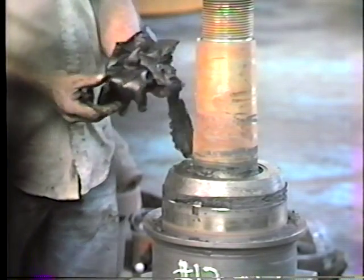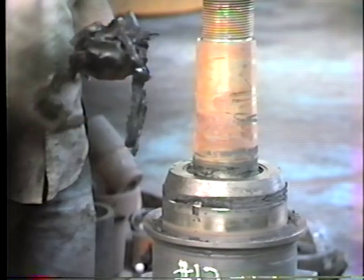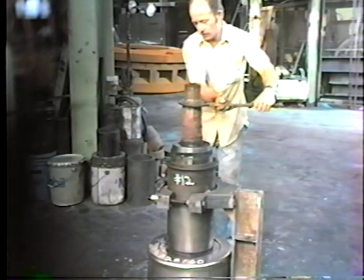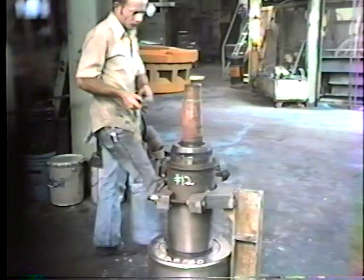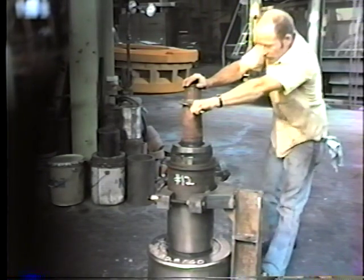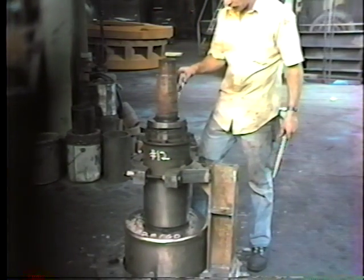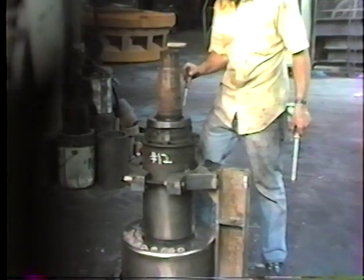Will the shaft rotate? Right. Okay, let's see if the shaft will rotate. Okay, it will not rotate. For the seal now, is there anything in there? That seal is missing right there. Pieces of the seal are missing. All right.